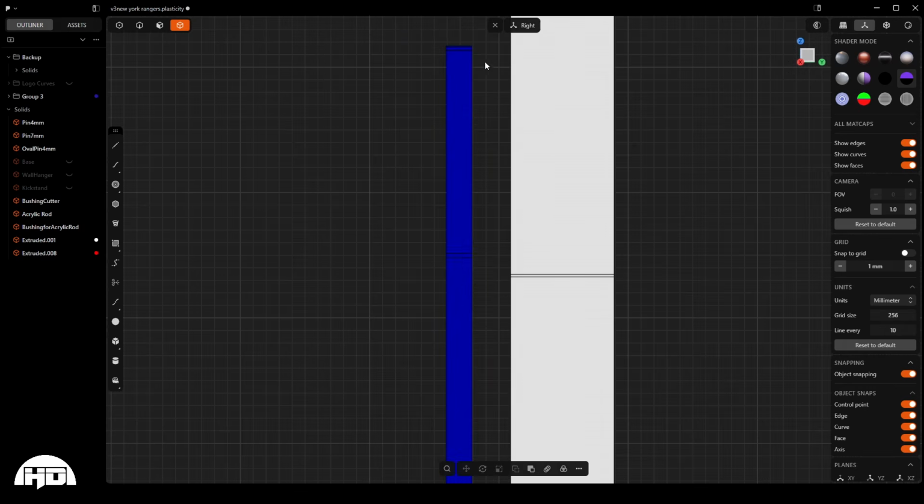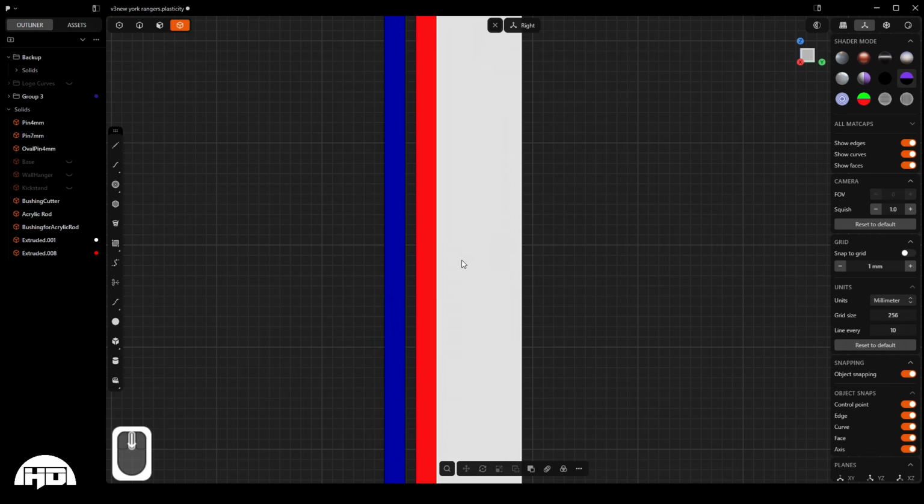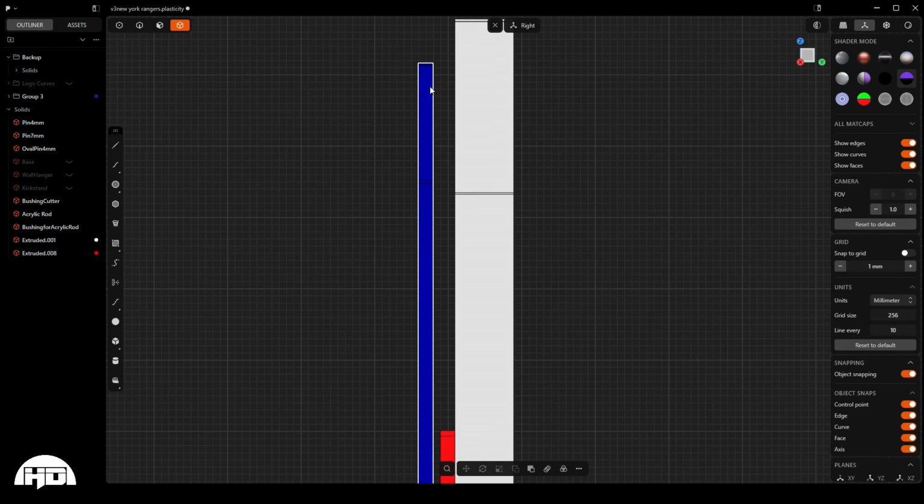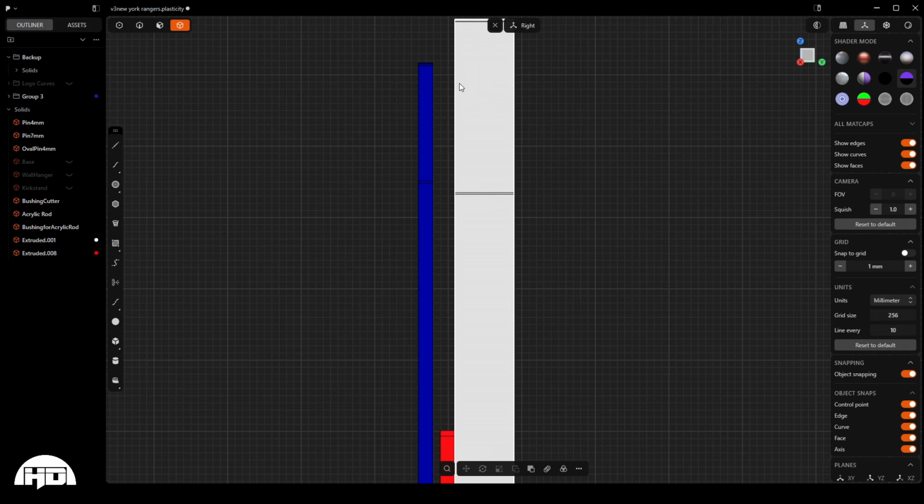So we have this one extruded. It's 2 millimeters, and we have it moved out 3 millimeters. So you can see over here in the outliner, I have 2 pin designs. I've got a 4 millimeter, and that's the length of the pin. And I use the 4 millimeter pin for anything that is set directly on another piece. So like this red piece, I'm going to use the 4 millimeter. So then that pin will go into this body 4 millimeters. This one will use the 7 millimeter, right? Because we moved it 3 millimeters out, and it will go into the body 4 millimeters.